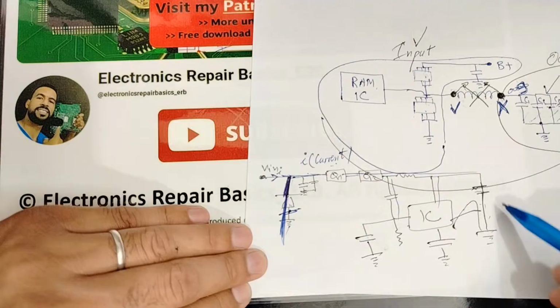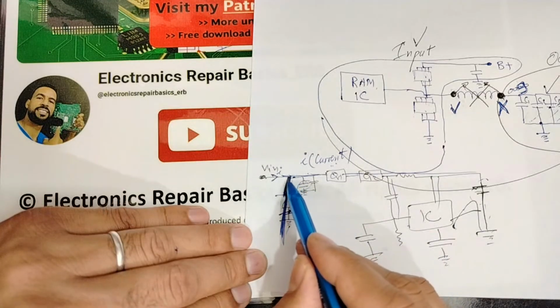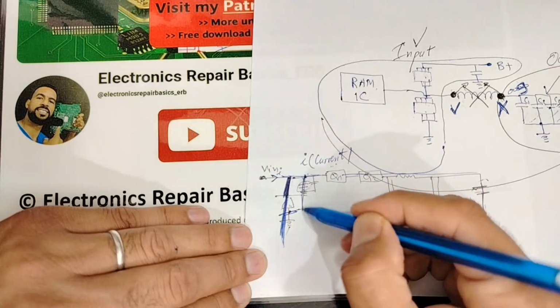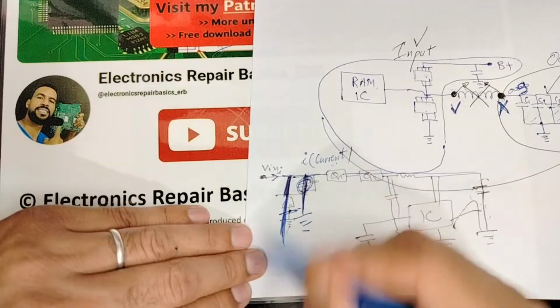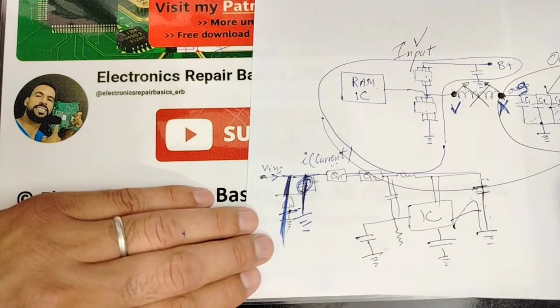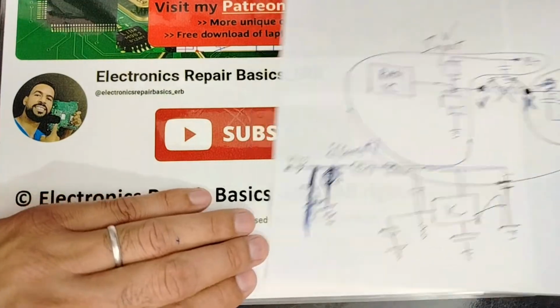But if this one is good and, for example, this one is the bad one, or this one for example is the bad one, it is the same: here a little bit of current, here a little bit of current, and here a lot of current, because this one is connected to the ground and this one will be very hot. This is how the voltage injector works. And of course, with the thermal camera you can see the hot components.